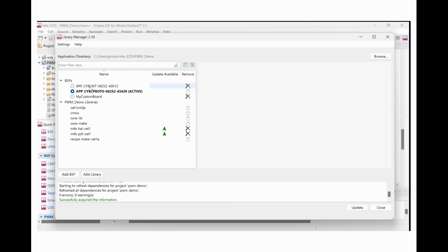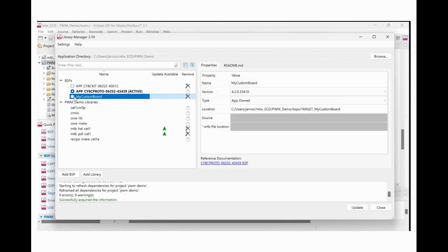These could be different boards, my own custom hardware. And by selecting these, I can tell the project, okay, this is now the implementation that I want to use. So remap all of those signals that we talked about to the actual physical pins that are on this particular board. So it makes it very easy to manage one application targeting multiple versions of the hardware, or development hardware versus actual product hardware.